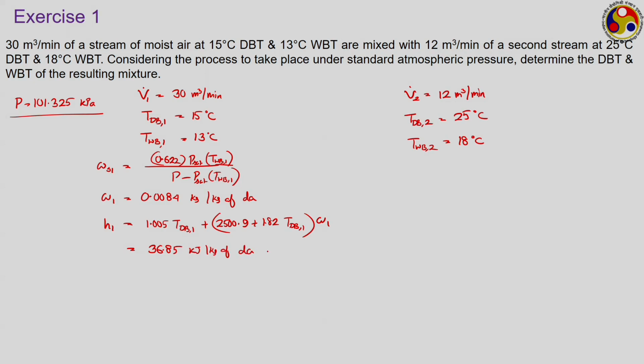The same way you can calculate the specific volume as well. For the dry air part, we need to know the specific volume, because we have to calculate the mass flow rate also. So, specific volume for dry air corresponding to 1, how much should it be? It should be R, sorry, the gas constant for dry air into T1 by P. Here T1 is put in Kelvin.